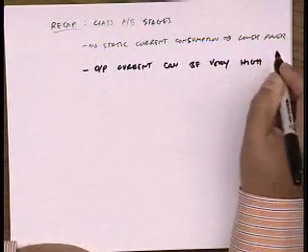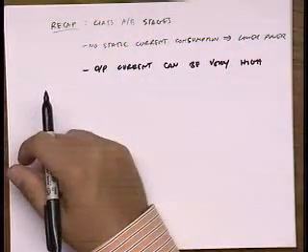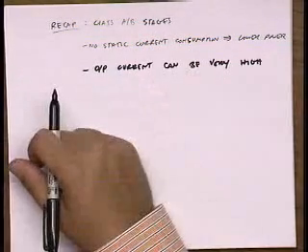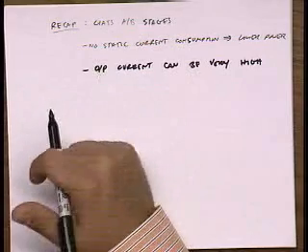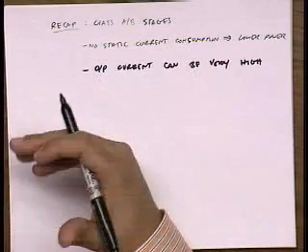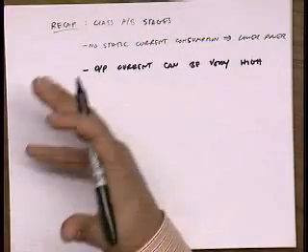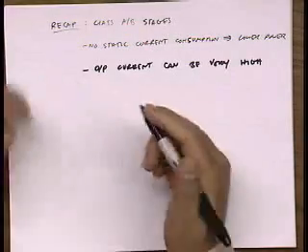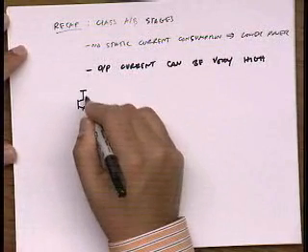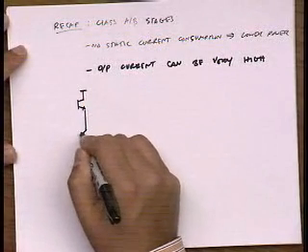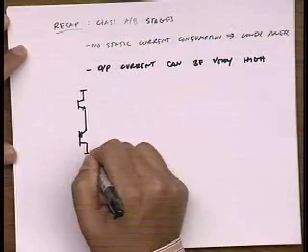In other words, if we designed an output stage that's Class A, the peak current we could get out of it was the bias current. Here, the peak current we can get out is really how much voltage we can deliver to the device. Obviously, the supply voltage is going to be a limitation. One of the output stages we looked at was basically two followers.